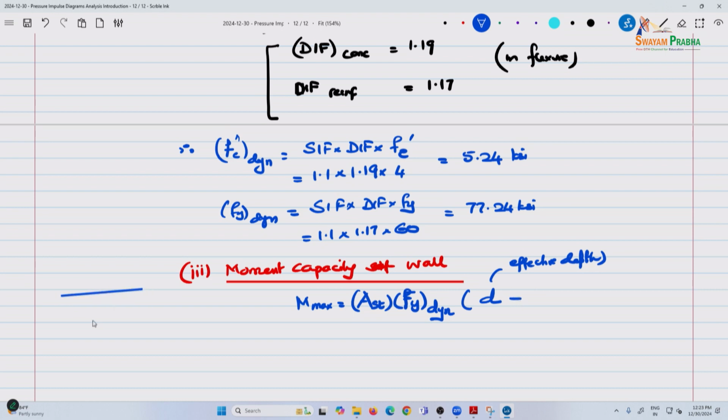So, here we have the steel, total depth is 8 inches, this is H, effective depth is D. This is the compression side and this is the tension side. Remember that we assume that anything below this, the tension concrete, does not exist, right. So, on the tension side, that is D, and this is the compression block.